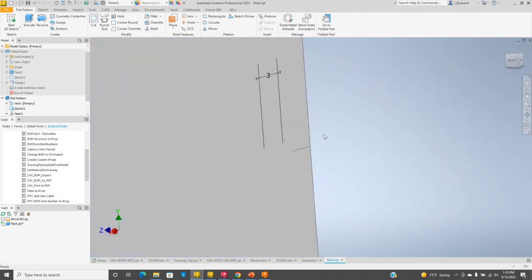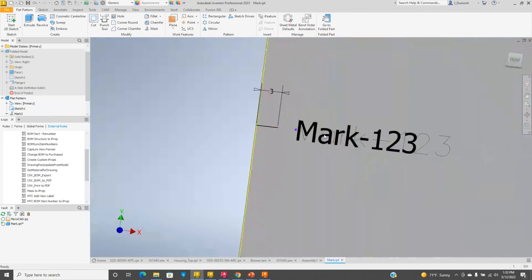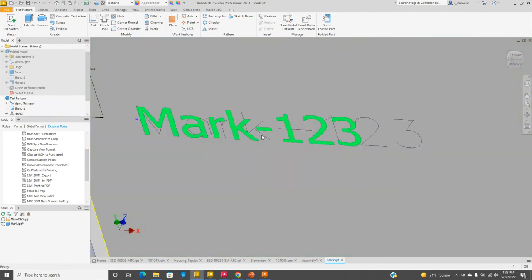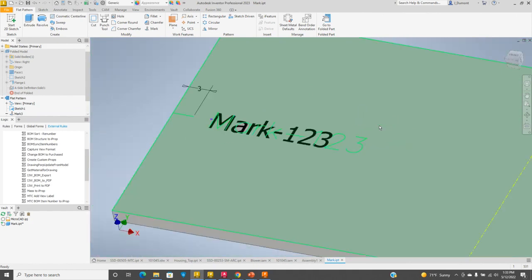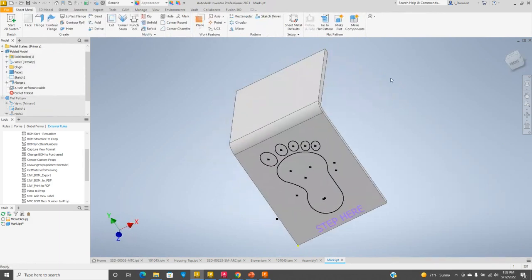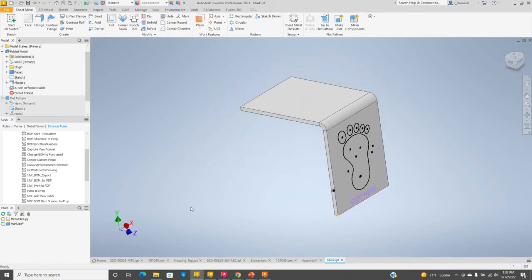Sometimes when you're etching, you want to go through the geometry, and a lot of times we only want it to be partial. So you can swap out whatever text the user is using to whatever text is appropriate for your engraver. And that is only in the flat pattern. It's the only time you'll see that, and it works really nice.